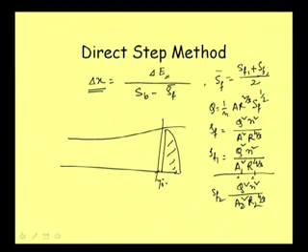Then, okay, I am writing this as 1, say. From this we can calculate this SF1, and we can calculate this y1 plus v1 square by twice g, meaning E1, we can calculate. Then we actually do not know E2 and SF2, that we do not know. So, what we assume, first we assume, okay, we want to calculate the delta x, but we do not